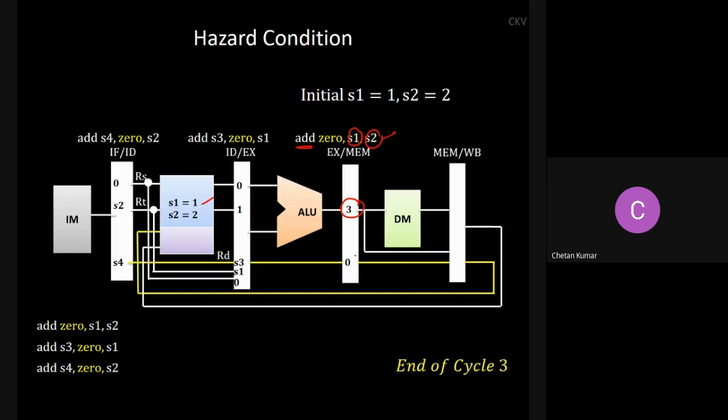And then the destination register is supposed to be 0. Now here, if you check the source of this instruction and the destination of the previous instruction, they are both the same. So your original condition is getting satisfied, so it will forward 3. And when you compute the sum next time, it will take 3 plus 1 and try to calculate 4 as the result of S3. Is this correct? No. So how do I avoid that?